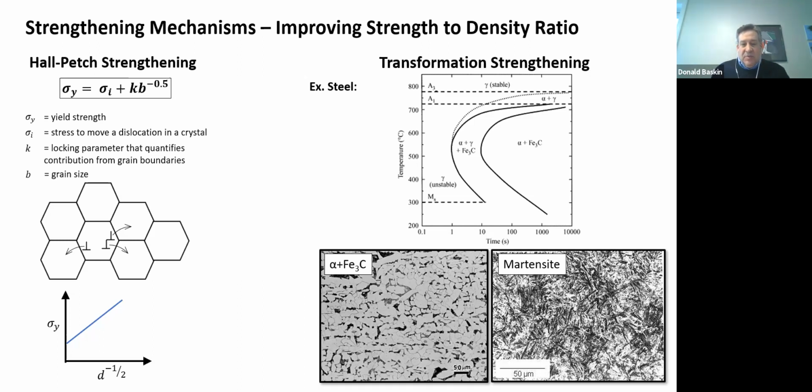One of the professors in your department, in the material science department, Professor Chris Hsu, started a very wonderful company where they found a way to make nanocrystalline nickel by painting these grains with a tungsten solution. So you can imagine a little grain of nickel, and then it has almost like a monolayer of atoms over it of tungsten that make it thermodynamically unfavorable for this grain to grow. So that's how you can preserve the grain size, because grains grow with temperature and time.